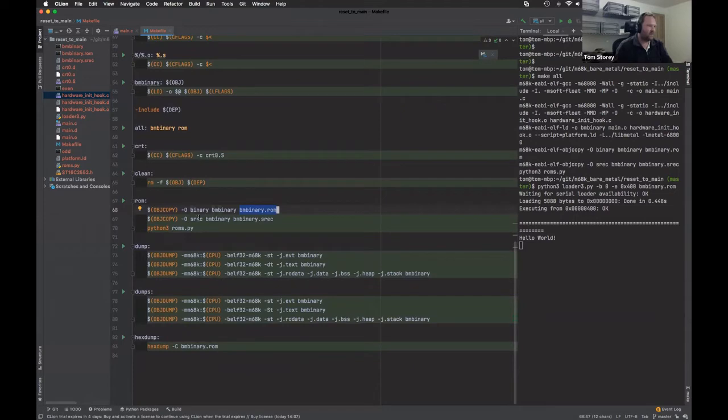John, to answer your question, yes, we can do srec files. I've actually had this in pretty much from the beginning of my toolchain, but we can use obj_copy to take the binary contents out of the ELF file in srecord format as well. So that could potentially be used to feed into making CPM binaries.